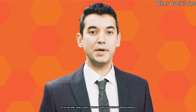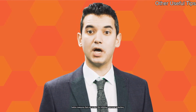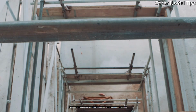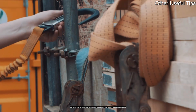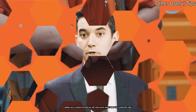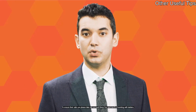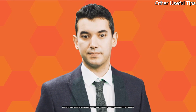As we said earlier, always consider measures that protect everyone at risk, collective protection, before measures that only protect the individual, personal protection. Examples of collective protection include permanent or temporary guardrails, scissor lifts, and tower scaffolds. An example of personal protection is putting on a safety harness correctly and connecting it with a lanyard to a suitable anchor point. Ladders are a common tool that you will come across when working on construction sites. To ensure their safe use, please take into account these do's and don'ts of working with ladders.